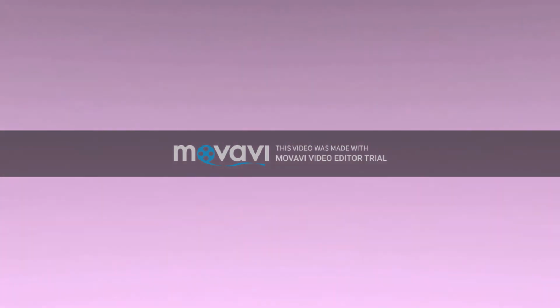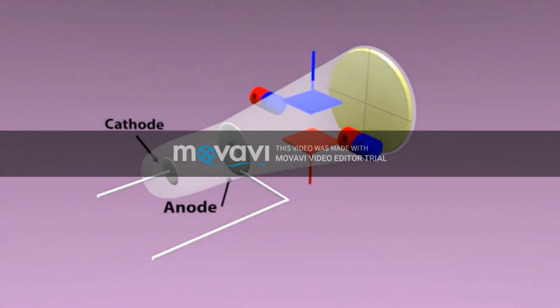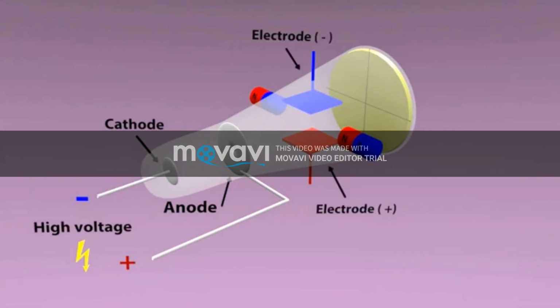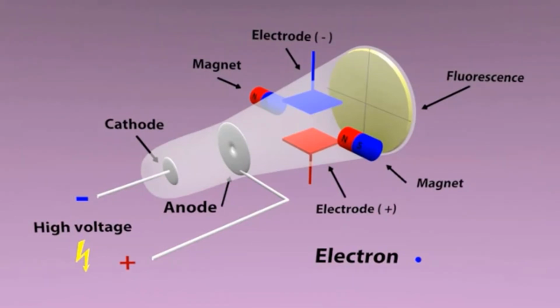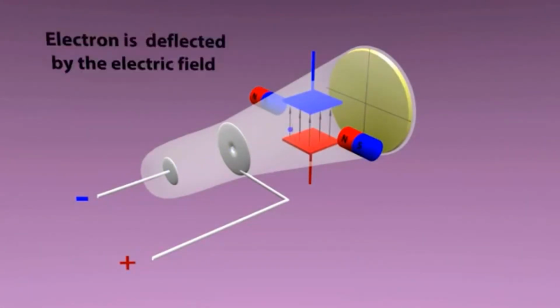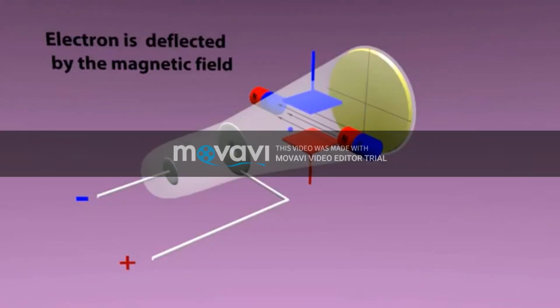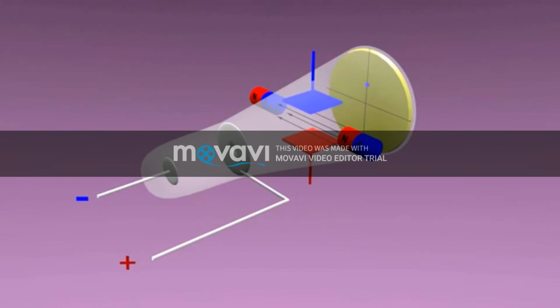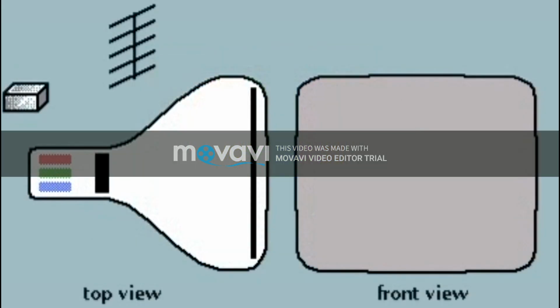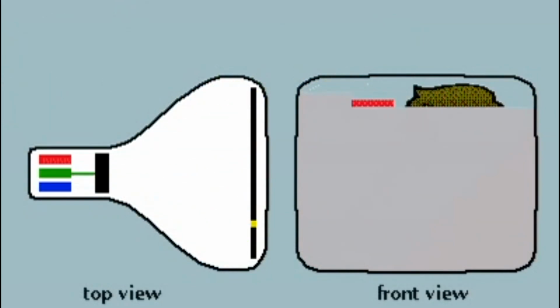Another application is an electron gun. It is mainly used in cathode ray tubes for old computer monitors, televisions, and ionization of particles. It is a specialized vacuum tube. It starts with a small filament that heats the cathode. Two anodes turn the emitted electrons into an accelerated beam, and finally it is focused by an electric or magnetic field to hit the phosphors in the screen that emit colors in each pixel and form the image.